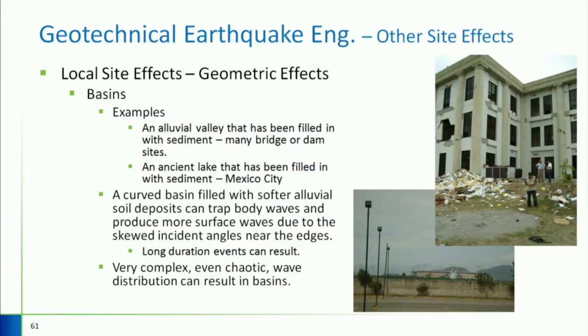And this is just an example of basin effects, because that swamp that was filled in with soil trapped these waves, and it bounced all over, and it created a more complicated wave when it hit that structure. It amplified certain parts that caused this building to deteriorate.